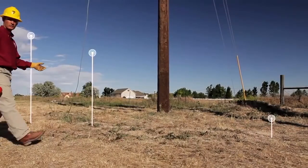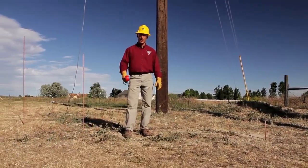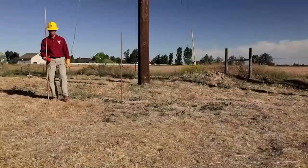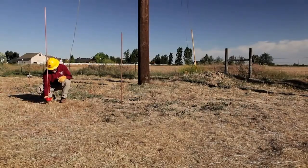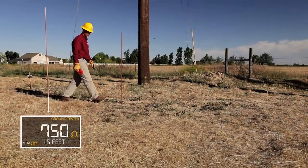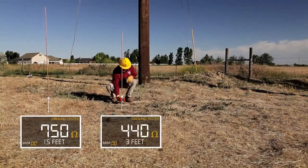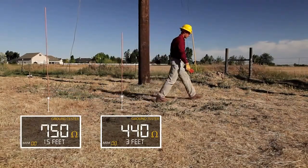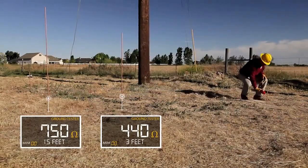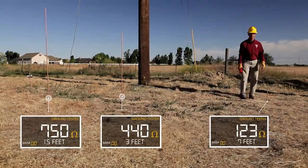Here we have a series of ground rods driven at different depths in the ground. And using this ground rod resistance tester, I'm going to measure each rod's resistance. Our first ground rod is only driven 1.5 feet deep and has a ground resistance of 750 ohms. Our second ground rod is 3 feet deep and has a ground resistance of 440 ohms. And our last ground rod was driven 7 feet deep and is reading 123 ohms. As you can see, the deeper the ground rod is driven, the less resistance it has.